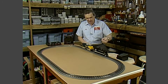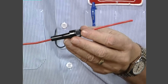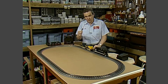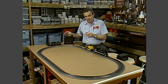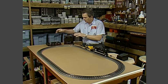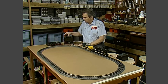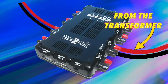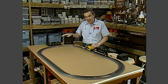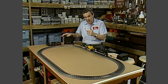One easy way to prevent damaging the TIU is to put inline fuses between the transformer and the TIU. These fuses will blow almost instantly when there's a short, much faster than the circuit breaker in these old transformers. I now have all the wires connected to the transformer, the TIU, and the track. Now if you look closely, you'll see that all I have done is change the wires so that the track power is now going through the TIU on its way to the track. Now when I turn on the power, the TIU adds the DCS digital command signal to the power.